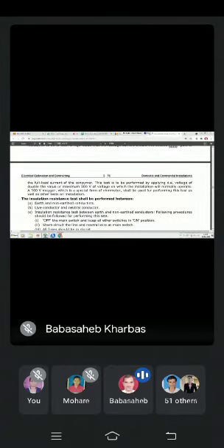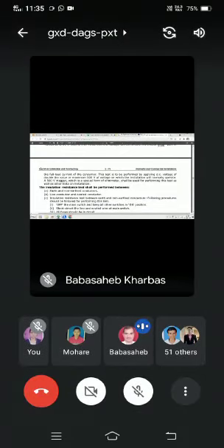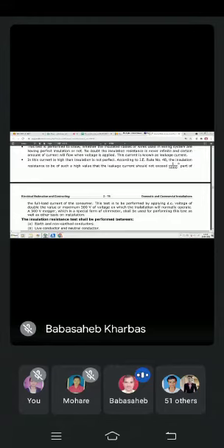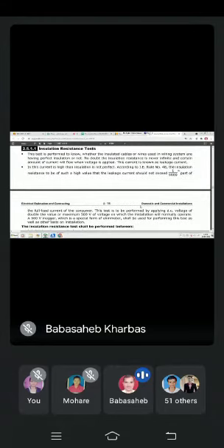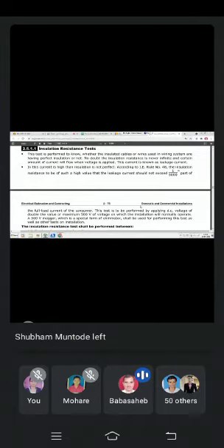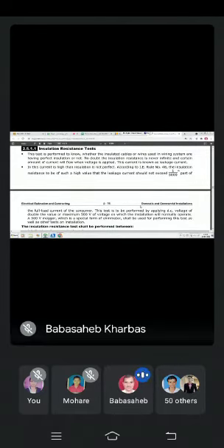You may record what we have. No insulation is perfect. That is very important. No insulation exists that gives you 100% zero leakage current. Keep in mind, leakage current is always there, but leakage current should not exceed 1/5000 part of the full load rated current.